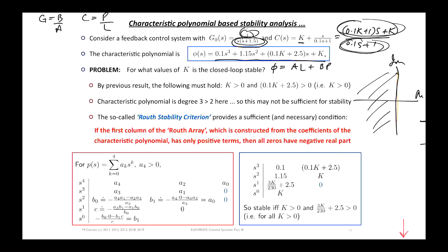So in the limit as s goes to 0, this goes to some constant, K times 100 on 1. So 1 on 1 plus lambda(0) will be 1 on 1 plus K times 100. So it doesn't go to 0, but as you increase K, the error goes down. Does that make sense? Yeah.